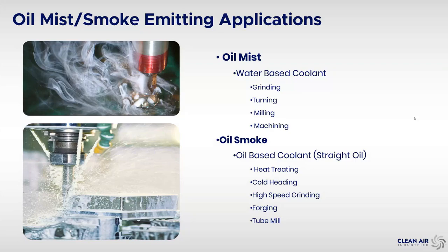Most of the processes that I've seen out there are mostly oil mist, which is your water-based, and they're from grinding, turning, milling, and machining. And so those are a little bit of a lighter mist, still just as dangerous as oil smoke, but the oil smoke is a little harder and has a lot more concentration. So it takes twice the filters to handle an oil smoke application as it does an oil mist.